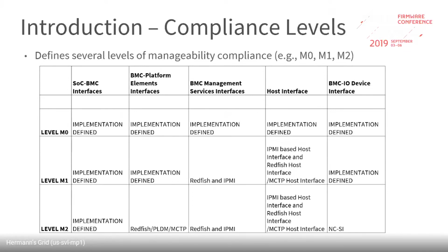For level M2, we have an SOC to BMC interface. It says implementation defined here, but we plan to use MCTP or SMBus as an interface between the service management controller and the BMC.